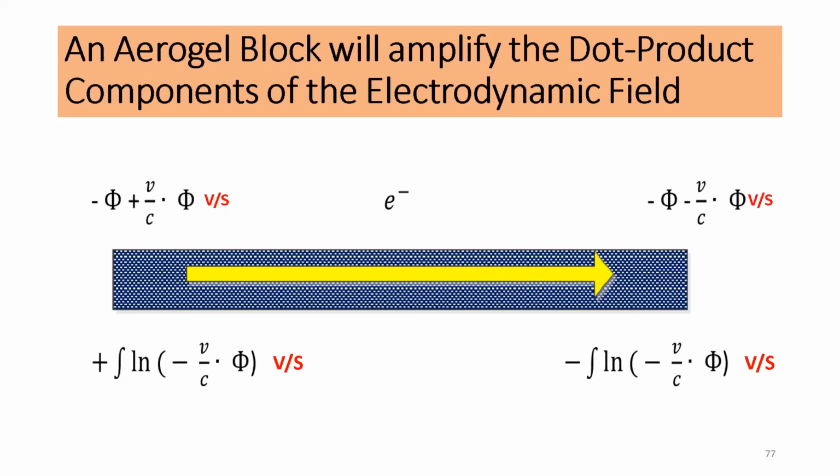You turn it on, and it builds up over a short period of time to a certain value, because eventually your isolators are going to spark over, or the charge is going to start leaking out somewhere. So the difference only gets to a certain point and stabilizes, but it does take a few seconds to get there.